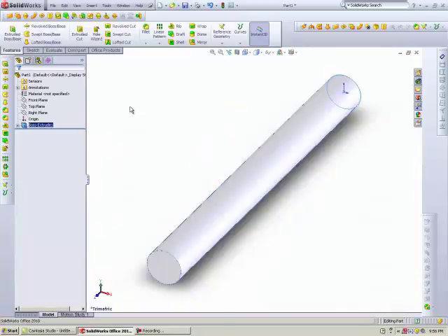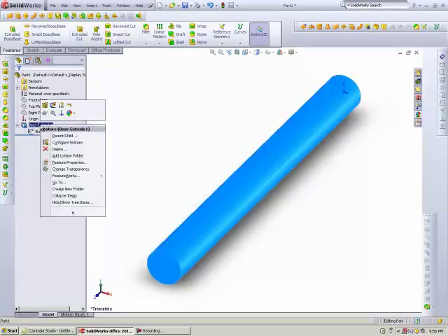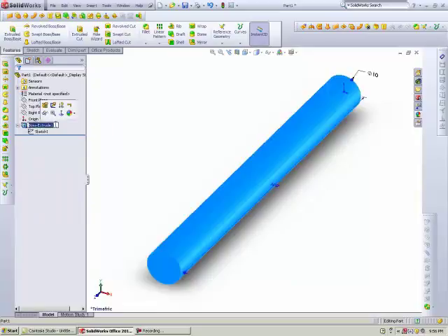Okay. Now, notice the Z direction, and if I expand the Boss Extrude, notice where my sketch is back here. So we want to extrude in the positive Z direction. Okay. Now, from the feature tree, I'm going to rename Boss Extrude 1, and I'm going to select it again and rename it to Base Extrude. Okay.